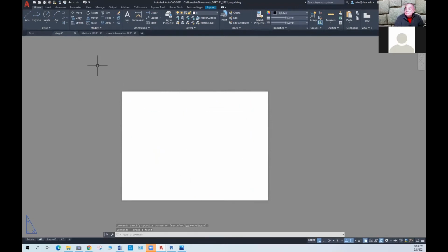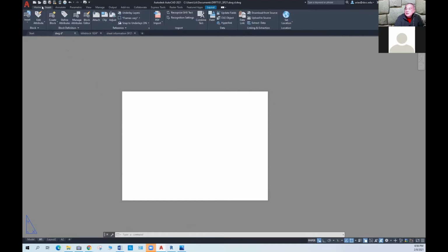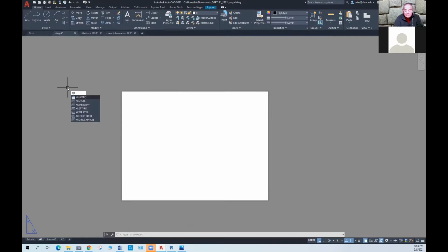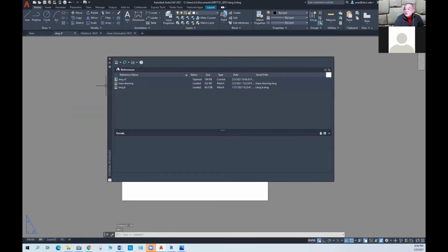And I'm going to bring in my title block. And see, this is the presentation that I need to do for next class. And so for drawing number 2, I am going to insert my title block. So insert xref, xref. And we're going to find the title block.